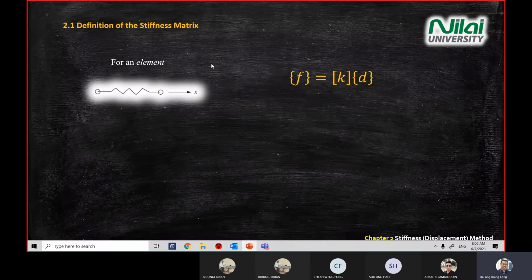Okay, so on these slides or on your screen here, you're seeing that we're using a small f, small k. D displacement is always a small letter, right? So only look at the form of the equation that we use. The first equation for today is F equal to KD. Force equals stiffness matrix times the displacement. All right. So F is the force, nodal force at here and here. D is the nodal displacement, which is here and here also. What is happening to this node? And then K is the stiffness matrix. So for today, we're going to focus on the K element.